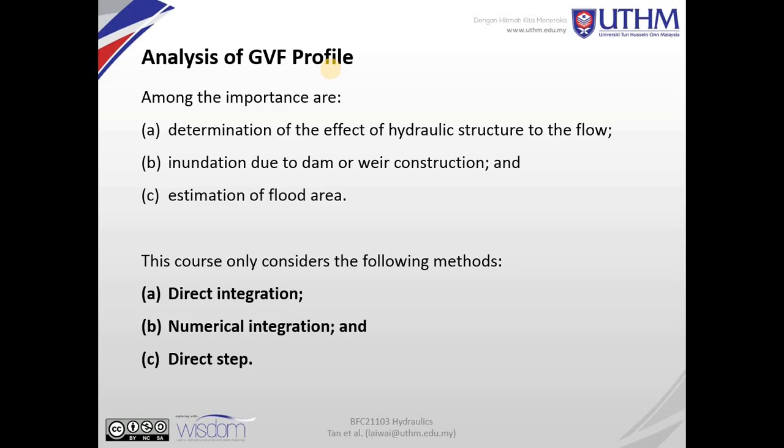And what is the importance of having a GVF profile in civil engineering practice? The first one is it can detect any changes of fluid behavior, especially when we install a hydraulic structure inside the channel. So depending on the case, the backflow profile is one of the GVF profile types, and the analysis of this situation can be solved through the GVF analysis method.